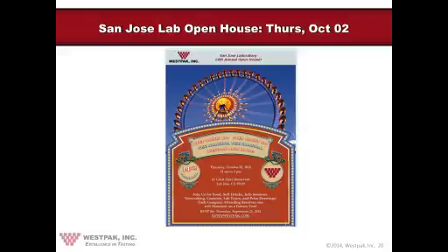We know that the smallest package, the smallest level of your package, is the worst case. So if you've got a stack of boxes, 100 boxes on a pallet, the pallet actually acts as a secondary package and adds a level of protection typically. You might argue that against compression, but even with compression, we know that the smallest shipping unit is often the worst case. So if it's going to get broken down into pieces at any time in the distribution cycle, then just test the single boxes. If those pass, you probably don't have anything to worry about when shipped on a pallet. But if it's only on a pallet and it's only shipped as a unitized load, then we should test just the pallet, because you don't want to over-test it if it's never going to get broken down.